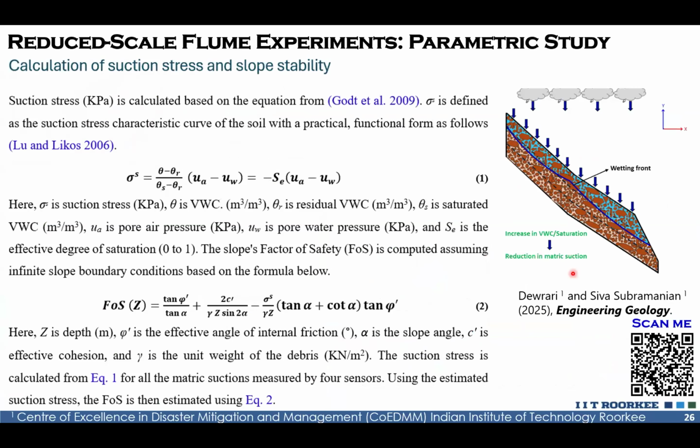Now, for the debris slide case, what we understand from the traditional soil mechanics textbook, if we calculate the suction stress, and use it assuming infinite boundary conditions for the two-dimensional cross-section, what we got from the experiments is that there is a possibility of calculating the factor of safety, which we did. The schematic shows an increase in volumetric water content and a reduction in matrix suction. That's found from the two sensors we installed inside the material during the experiment.